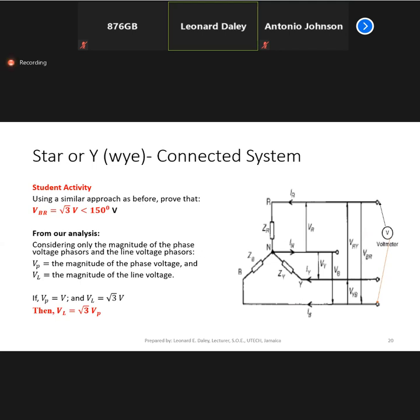I hope you're with me. If the phase voltages are 100 volts, VR, VY, and VB would all be 100 volts in magnitude, at 0, 240, and 120 degrees respectively. Whereas the line voltage, if the phase voltage is 100, would be 173.21 volts.